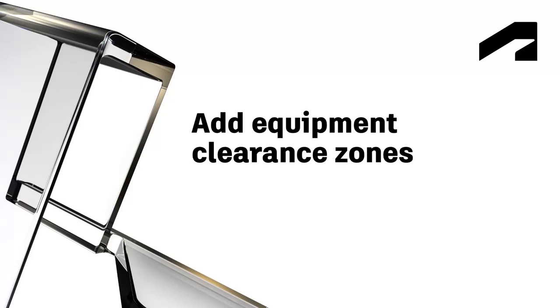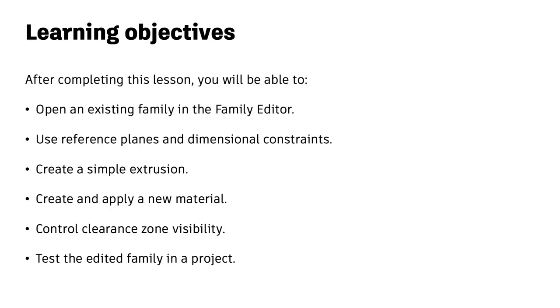In this video, you will open an existing family in the Family Editor, use reference planes and dimensional constraints, create a simple extrusion, create and apply a new material, control clearance zone visibility, and test the edited family in a project.